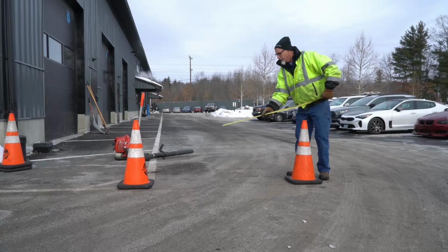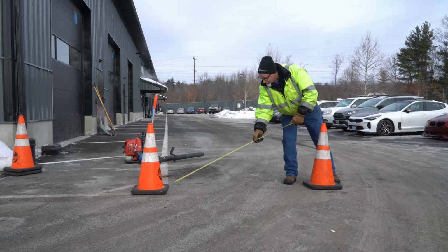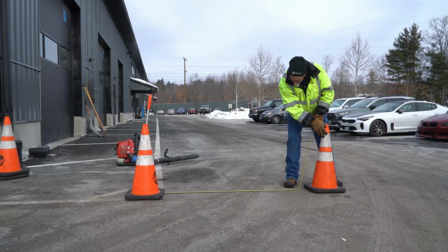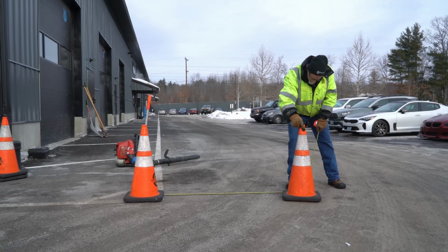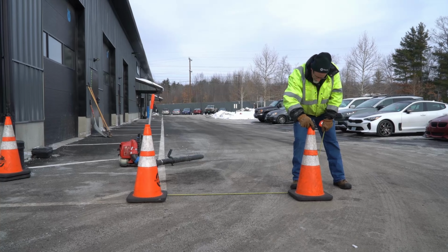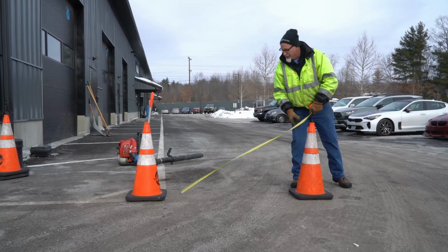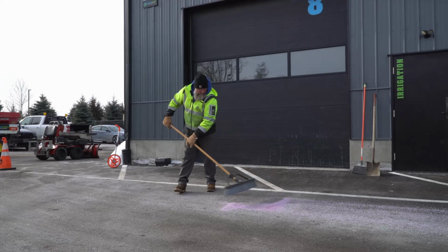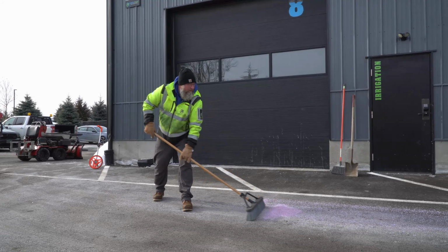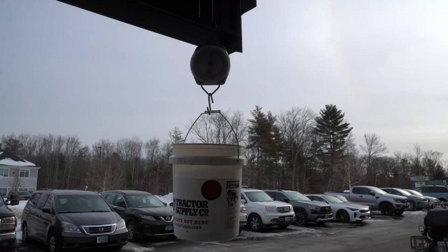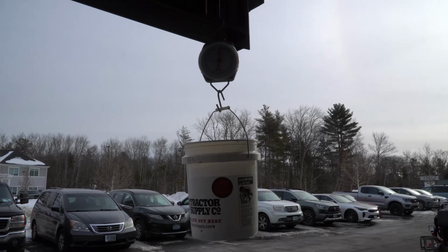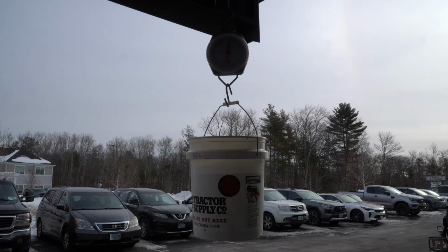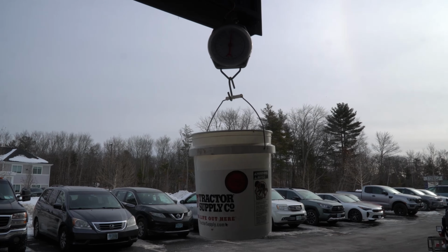Another option for moving verification is the sweep test. Unlike live route testing, sweep tests can be completed in a controlled area, such as a yard or parking lot, often during your pre-season setup. To complete a sweep test, apply material over a measured distance, run the truck at operating speed and preset, recover as much material as you can from the test area, weigh the recovered material, and calculate the pounds per lane mile. This provides another way to verify in-motion performance under controlled conditions.